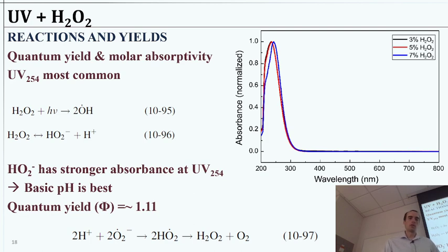If you shine light on it, it will start decomposing typically. So our typical mercury lamps at 254 can do a decent job at splitting it. And if we take a look at the absorption spectra, so if we're giving that light right around here, we can see that that's a pretty good spot within the absorption spectra. If we shift to maybe UV LEDs that shine a little bit off to the side, it's not going to be as efficient. So not the best candidate for changing wavelengths unless we went lower, perhaps. There's some challenges with that. Okay, so what's going to happen then is each peroxide can be split into essentially 2 hydroxyl radicals. So it's very efficient, convenient.